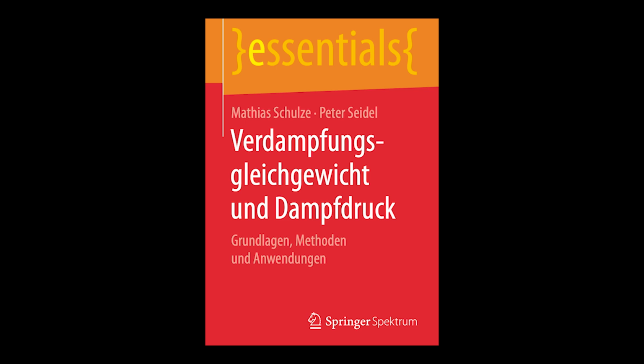First, you have compression. Liquid water from the condenser is compressed to a very high pressure. Second is isobaric heating and isothermal vaporization in the boiler. Immense heat is added at constant pressure to turn the water into saturated steam. Third is superheating. More heat is added to raise the temperature well above saturation, creating that dry, superheated steam. And then it goes to the turbine.